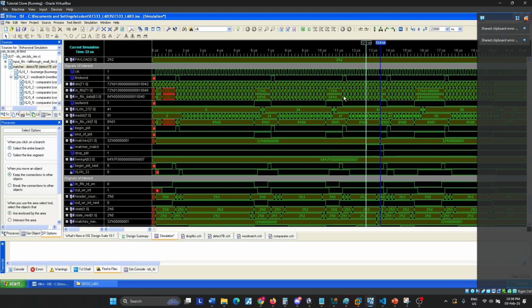It said I'm 41 at this particular point, and the write pointer kept increasing 42, 43, 44 because the number of packets entering into the system continuously increases. The moment there is a drop packet signal becoming 1, our write pointer basically updates. This history write pointer takes our memory write pointer to the location where the packet was not to be dropped, which was 41.